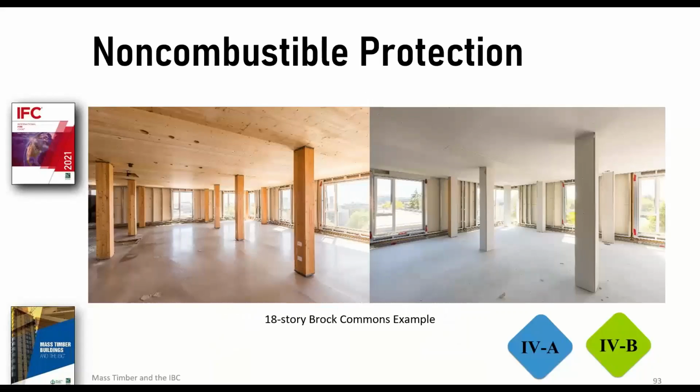Now, this is really based on what was done up in Vancouver, British Columbia. The 18-story Brock Commons mass timber hybrid structure incorporated techniques of adding non-combustible protection on floors below active construction level. Protection included 1 layer of type X gypsum board onto the underside of the CLT panels.